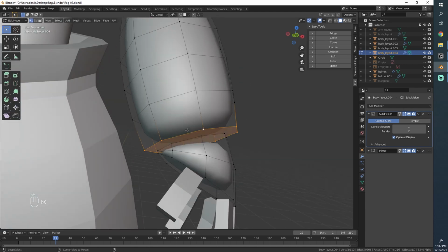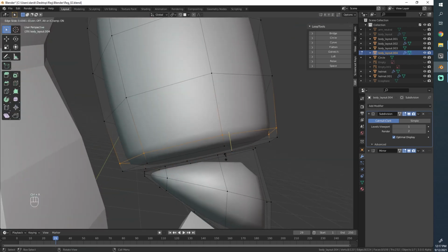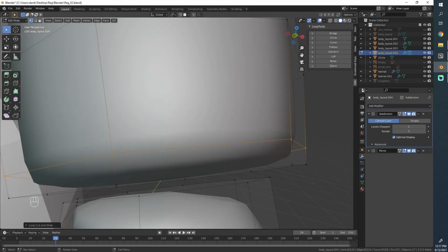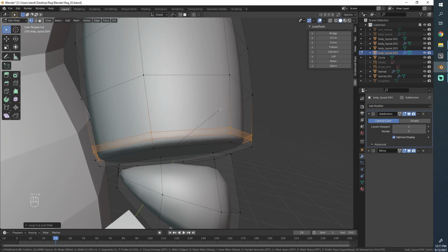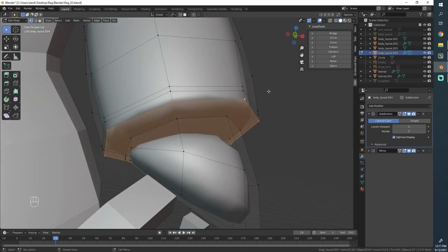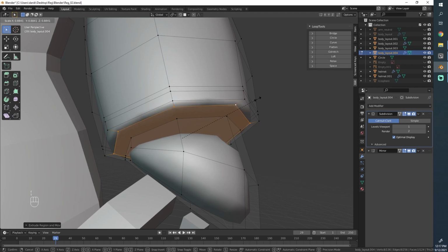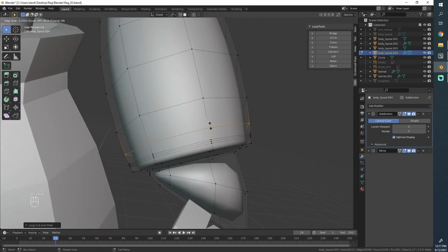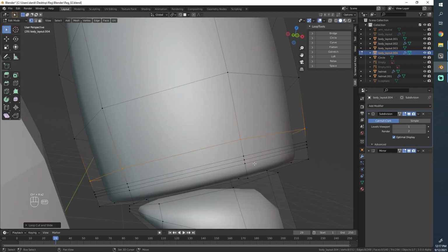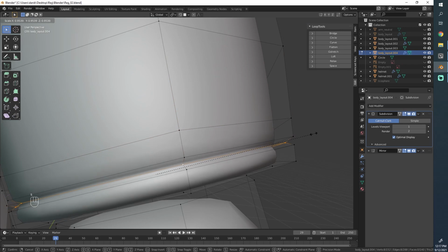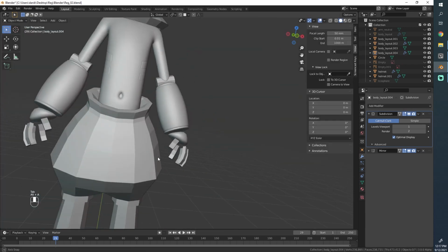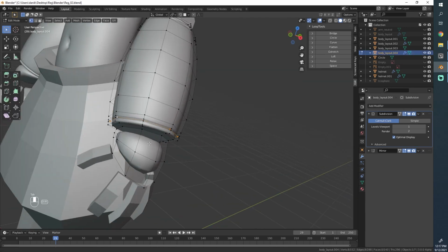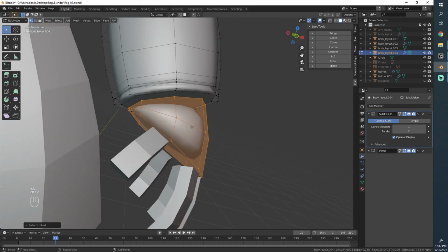And we're going to take a similar approach on this side. So let's insert subdivision here, or insert a loop cut. I'll bevel it. I'll take this part, extrude it, and scale it down a little bit. And then I'll also insert a loop here. I'll insert a loop with about the same distance over there and scale this part down. Now there we go. This is one part now detailed. Let's move on to the next one, which is this one here.